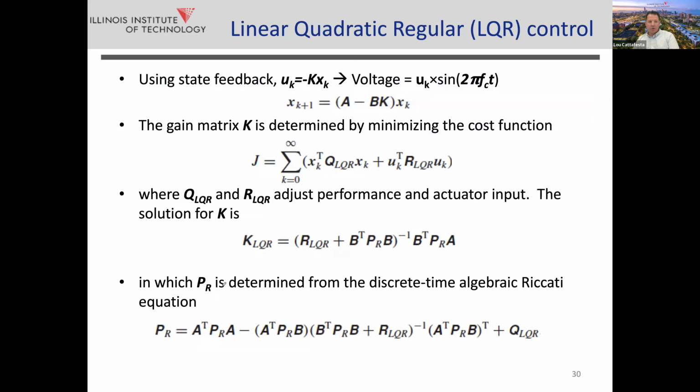So let's first talk about LQR. This is a standard linear optimal control approach. Just to refresh your memory, or if you're not familiar with this, it's pretty simple. Imagine you have some states, and with a linear quadratic regulator, we're measuring the states, in this case the states are what's measured by the microphone array. So using negative feedback, this is our control. Well, what is the control? It's actually some amplitude. Remember, I talked to you about a burst modulation that was a square wave signal, and we're running the actuators at their carrier, their high frequency resonance signal. We just want to change the modulation amplitude.